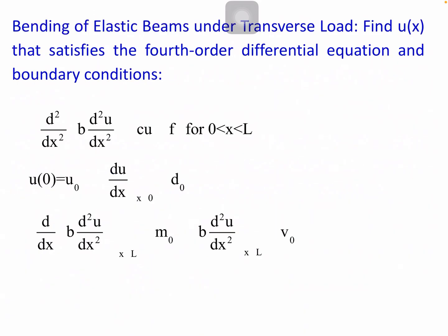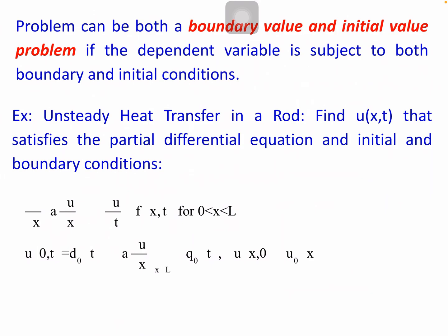Next. So in a boundary value problem, okay, you want to find out the integration constants, right? We give the boundary conditions. So what are the boundary conditions? I think last year you saw the double integration method, Macaulay's method, you solved the deflection problems. There at x is equal to 0, deflection is equal to 0, right? At x is equal to L by 2, slope is 0 in simply supported beams. Such conditions we give. They are called boundary value problems, right? So these are some examples of boundary value problems.